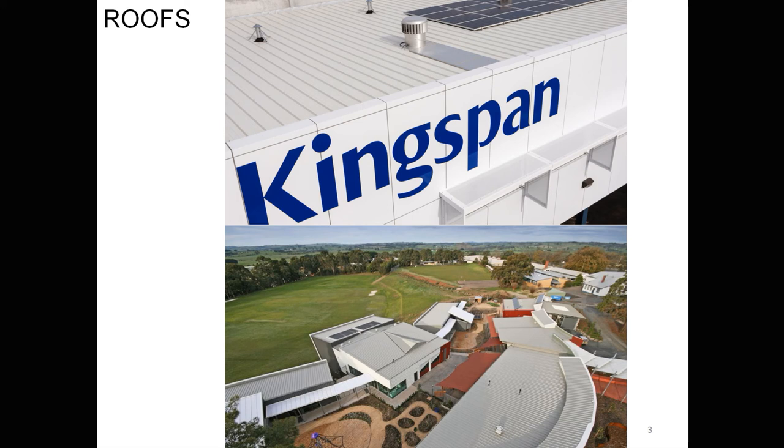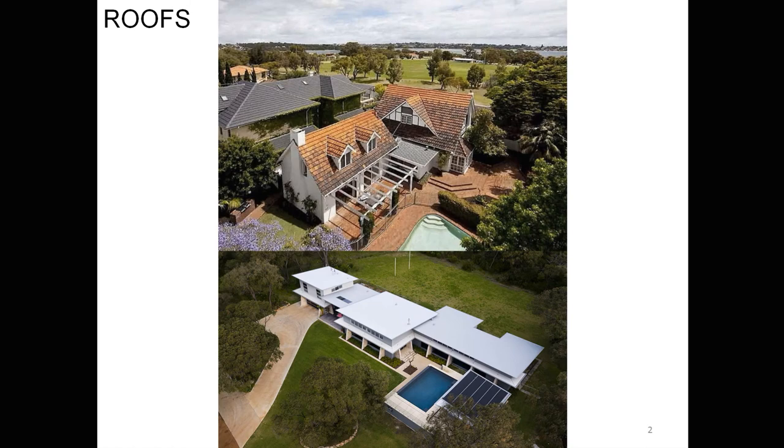One of our problems is that the main reference for this is something called the Lysaght reference, which is on the Moodle, and of course we have to take into consideration that they are trying to sell their products as well as give us good information to use. When you look at a roof like this, it is unlikely that any of the standard products will be adequate to drain it, because they are really designed for roofs like these, domestic tile and steel roofs.